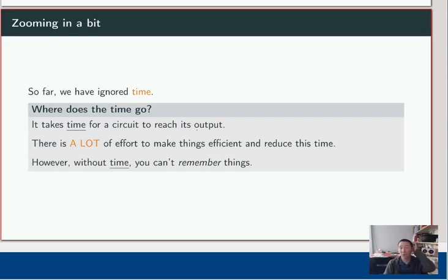Up to this point, we've ignored time. We haven't thought much about it. We've just said circuits work. And in fact, that's how combinational circuits work. There is no sense of time. You simply give the inputs. The outputs are there. It doesn't matter what any set of previous inputs were. If you had a 0 before, now you have an input of a logic 1. It doesn't matter. The NOT gate's just going to invert. It doesn't care. When we add time, that is no longer the case.